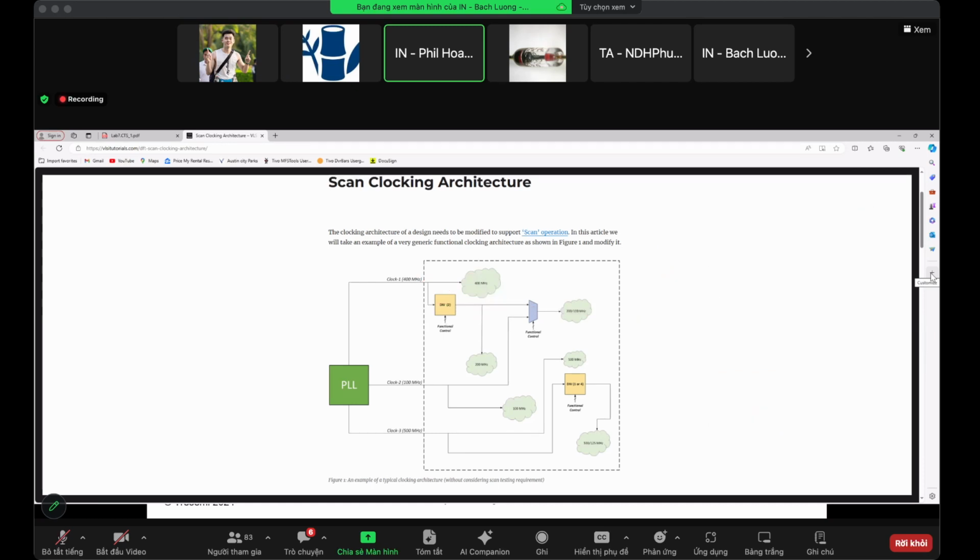So at the end, it looks at here and says, I have sync pins here, and I have sync pins here as part of one big clock tree. So it will try to skew balance between these two pins. That means it will skew match, right, between the flops here and the flops here. So the trees that go through the clock dividers to the flops will have to match the delays of all these buffers. These buffers and the delay through here have to match, unless you say this and this are two separate skew groups, then it won't try to balance between them.